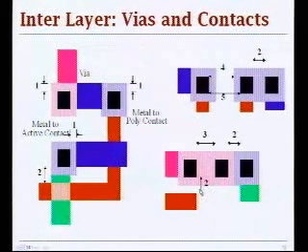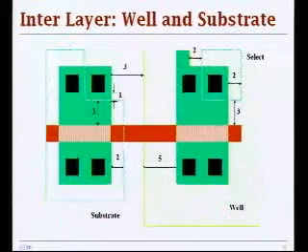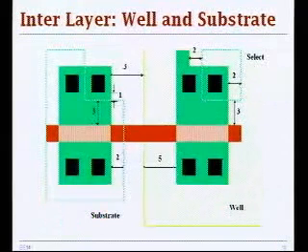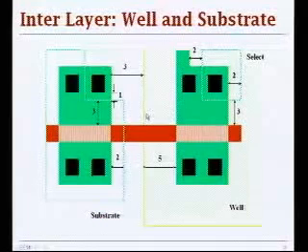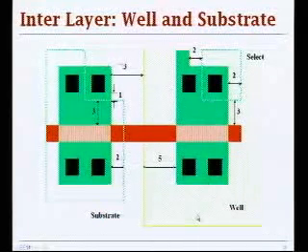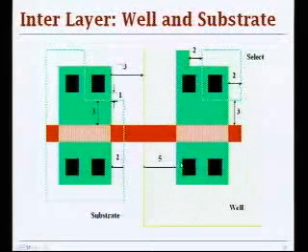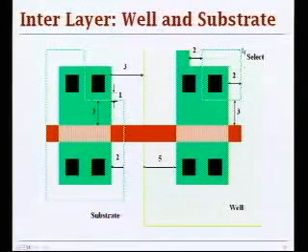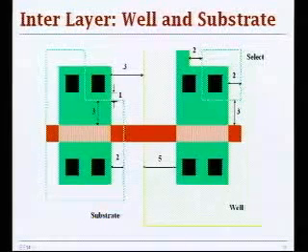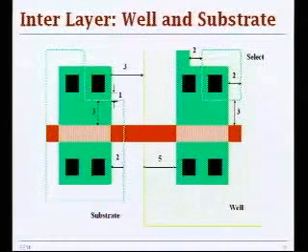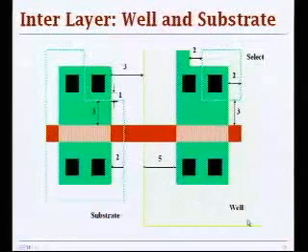And also finally we have our substrates that we need to connect. As I mentioned, that is done through this select layer, that you have basically a well. And if this is, for example, an N well, and this is your PMOS, you have P diffusion here with the select layer. It simply inverts the diffusion and provides an N plus area that connects to the well.